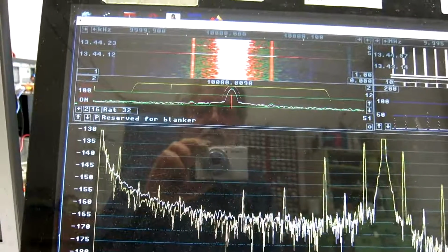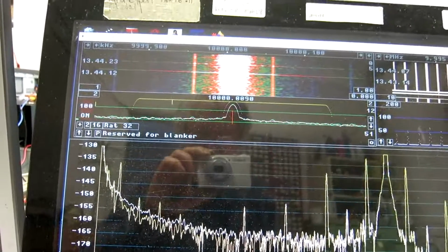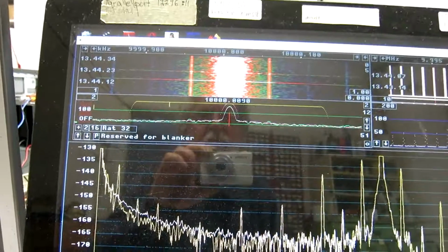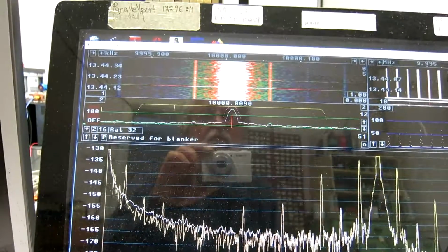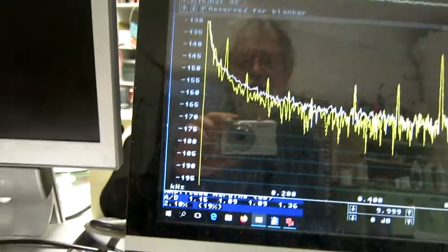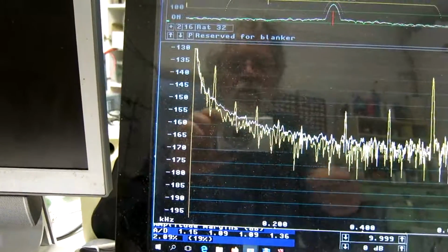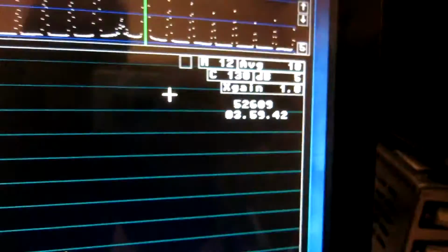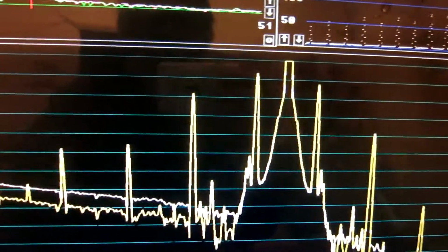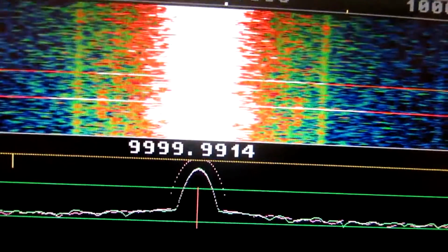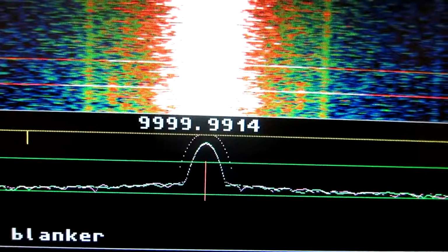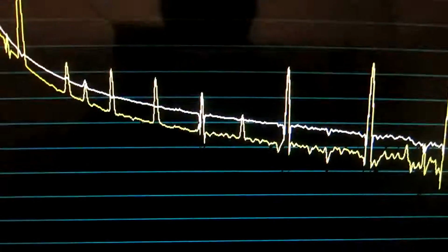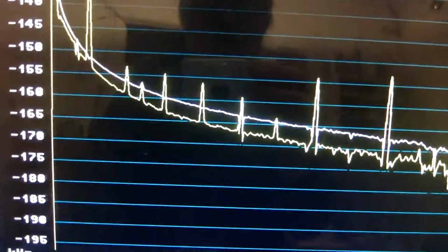The power is still 1 watt and I'm feeding the full power of the Wenzel into the amplifier. And I still have 15 decibels attenuation on the output. And the signal level is very closely the same as I had when it was an oscillator. 4 hours as an amplifier at an output power of 1 watt. There are these narrow band noise bursts also when the unit is running as an amplifier. As you can see here, the spectrum looks similar to before.